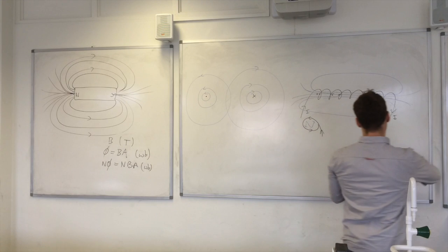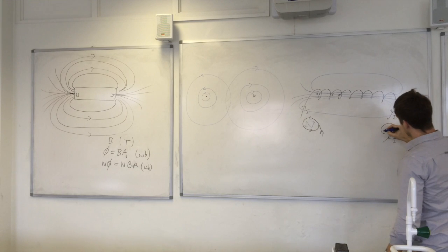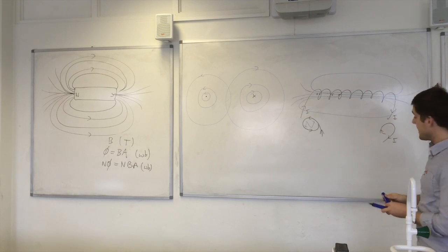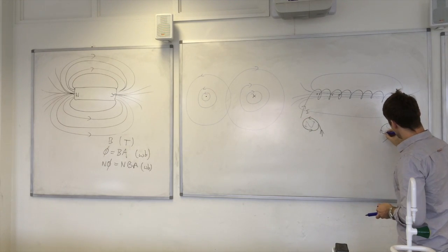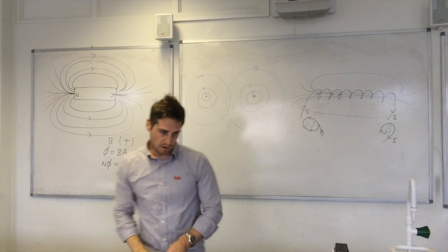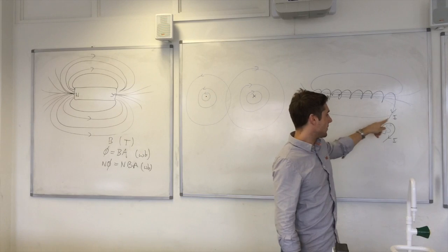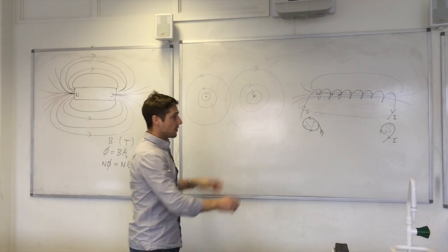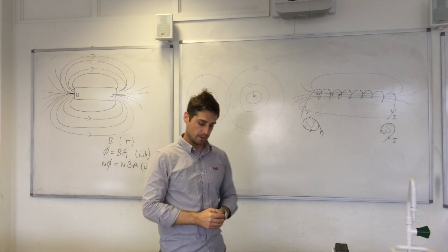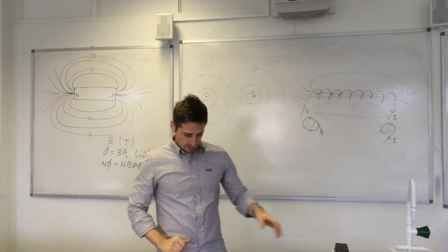And if you look at this end, here we have the coil rotating around and then going down like this. At this end, if you were to draw an S in there and put arrows on the end again, then they match up there as well. So at north, the current will be going anti-clockwise, and at south, it will be going clockwise. So that's a useful tip to remember for finding out the magnetic field direction for a solenoid. Okay, so that's our magnetic field patterns.